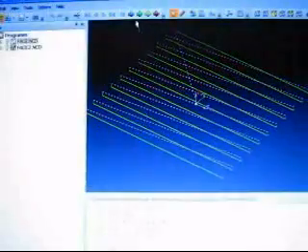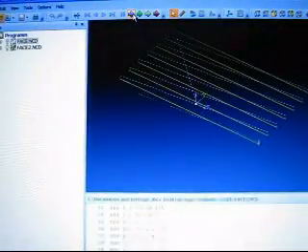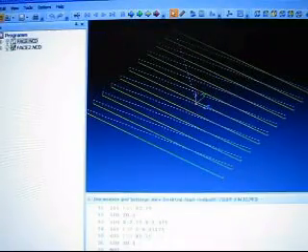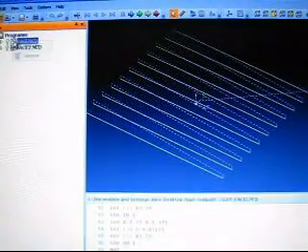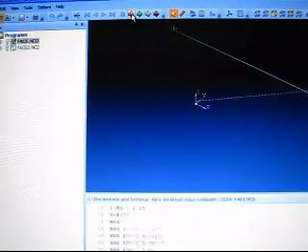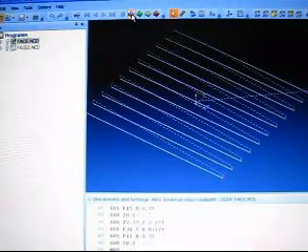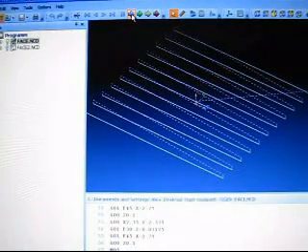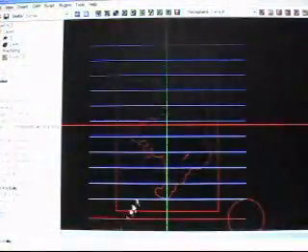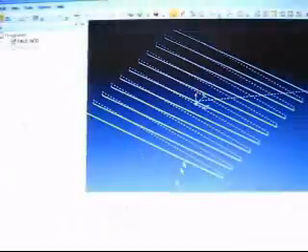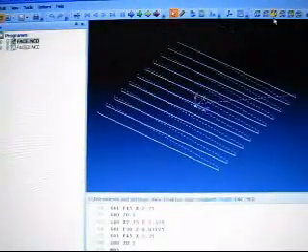And I mean, climb cutting in that direction depends on how you draw the line. I cut this part with a conventional cut. I wanted to give that a try to see, as there are advantages to both. Conventional and climb milling both have their advantages. There's a lot to learn online about that. It's pretty basic stuff. So that's the basic facing operation.